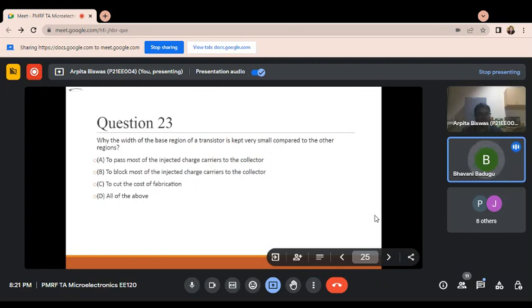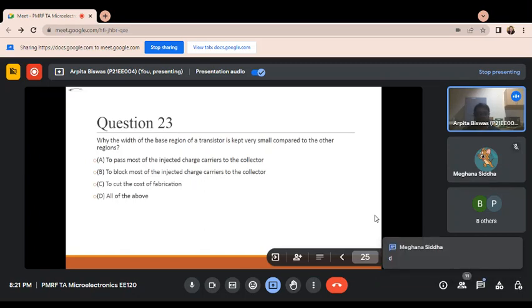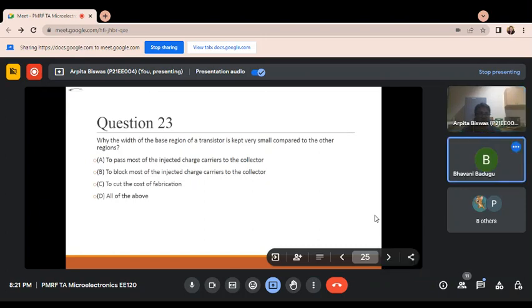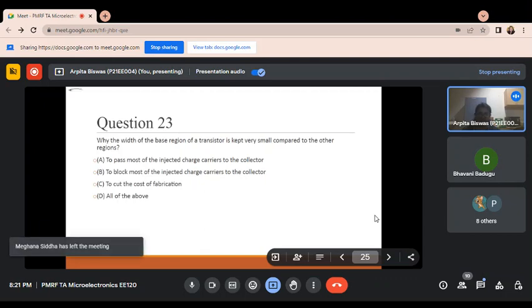Once again, can you explain, if it is an NPN transistor, what happens in that case? N type means the majority carrier is electron. Two things matter here, like the doping. In the emitter, the doping is slightly more than on the collector side. As the majority carrier is the electron, the doping is greater in the emitter side, and the base is p type.